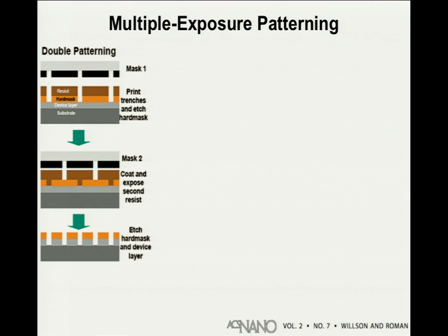You do this by a technique called spin coating, where you take your giant wafer and you extrude a polymer solution on the wafer, and then you spin it at several thousand RPM, and you expel all of the stuff off of the wafer from the edges, and the film becomes very thin and very uniform. That's how you get the photoresist film on the wafer to begin with.